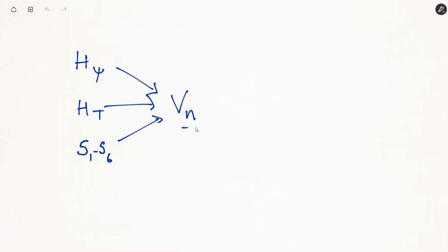So these three logics will govern our voltage vector output. That will tell us which switch of the inverter will be on, and accordingly, depending upon the pulse patterns, we'll have that much voltage fed to the inverter, which will result in control of speed and torque of the induction motor. So this is the basic control strategy of DTC, direct torque control, without going into much detail.